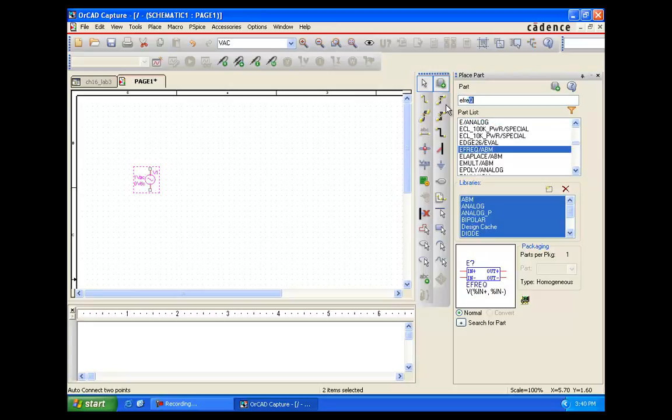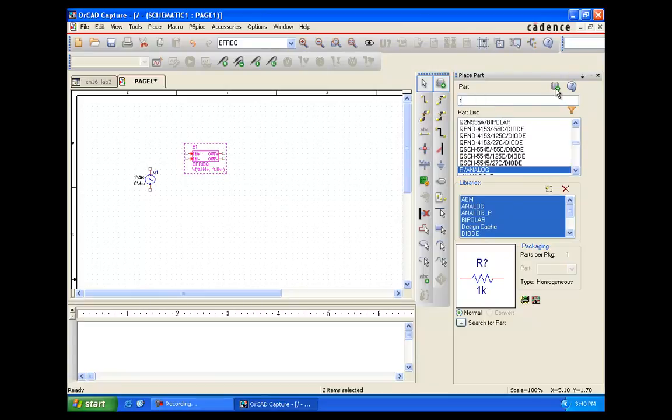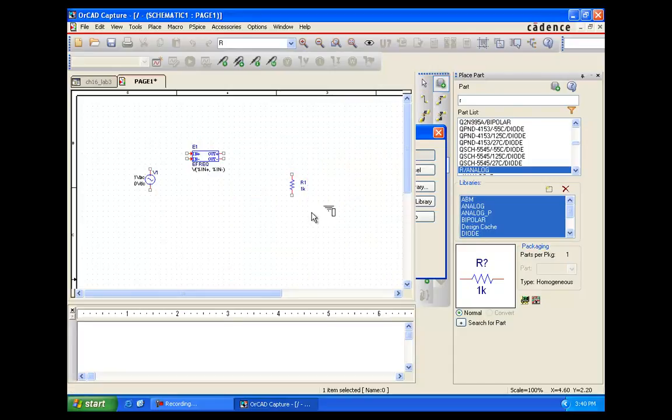The table's values describe a low pass filter with a response of 1, meaning 0 dB, for frequencies below 5 kilohertz, and a response of 0.001, which is minus 60 dB, above 6 kilohertz. The phase lags linearly with the frequency. So we are going to make a lookup table from 0 to 5 kilohertz, and the output we see from the other end.